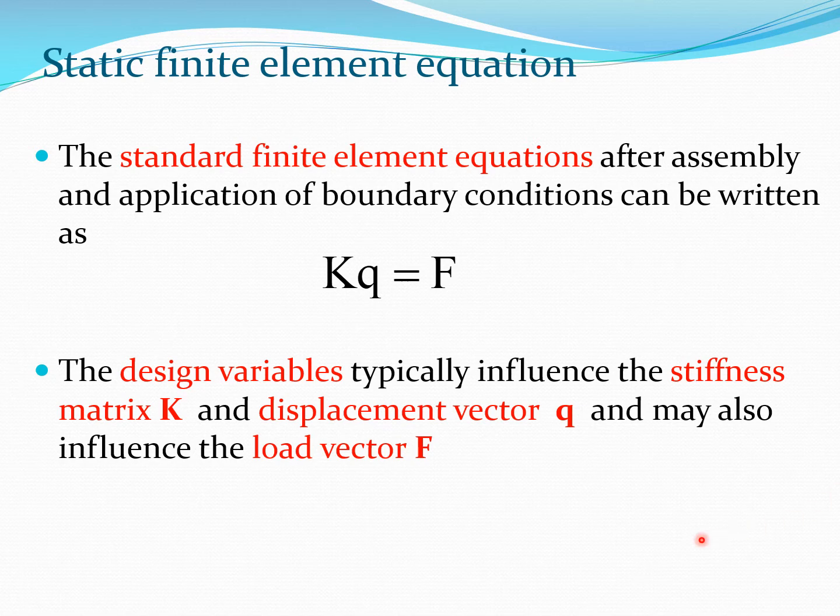So in all these cases, there are a vast number of methods out there to discretize the partial differential equations. What these methods do is discretize the partial differential equations, apply boundary conditions, and in the end you get a system of equations of the form Kq equals f, where K is known as the stiffness matrix, q is the displacement vector, and f is the load vector.